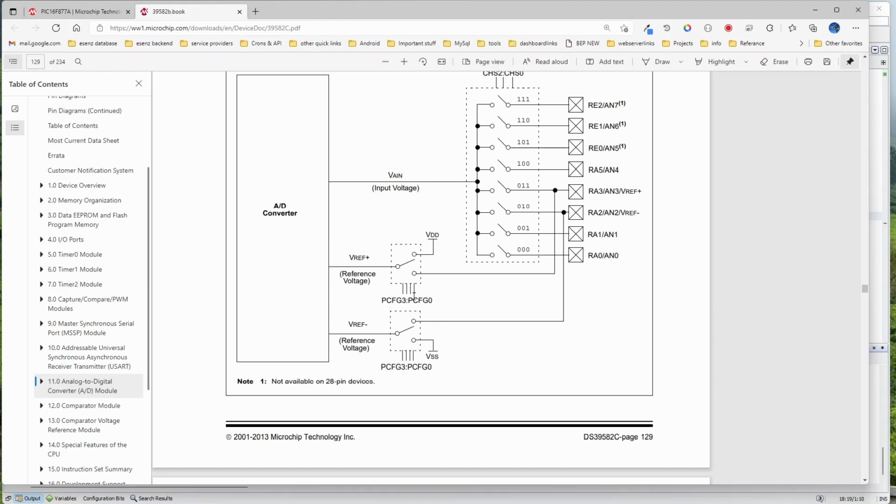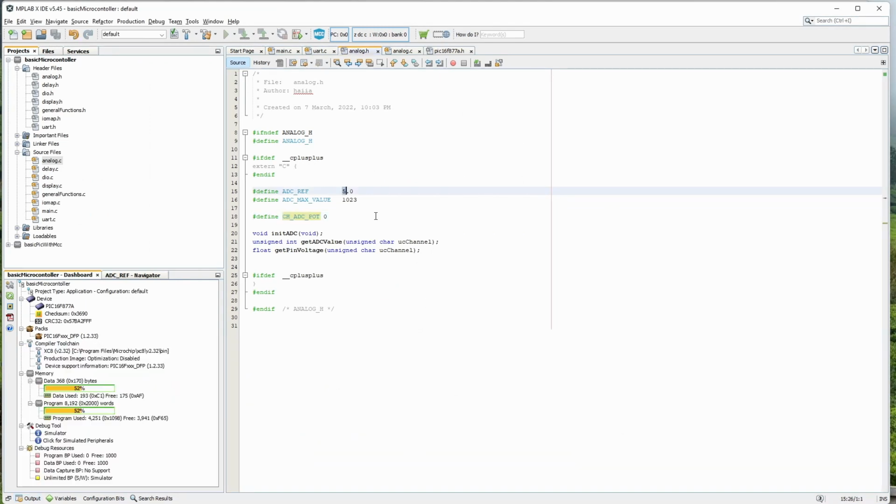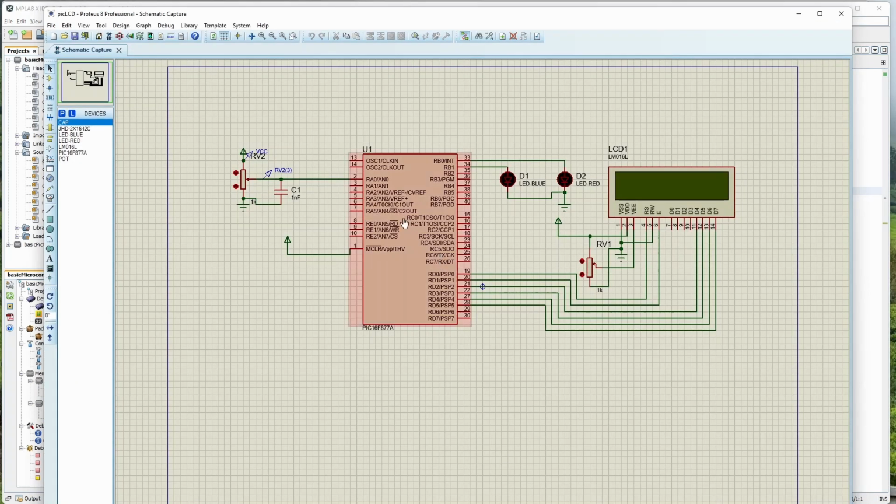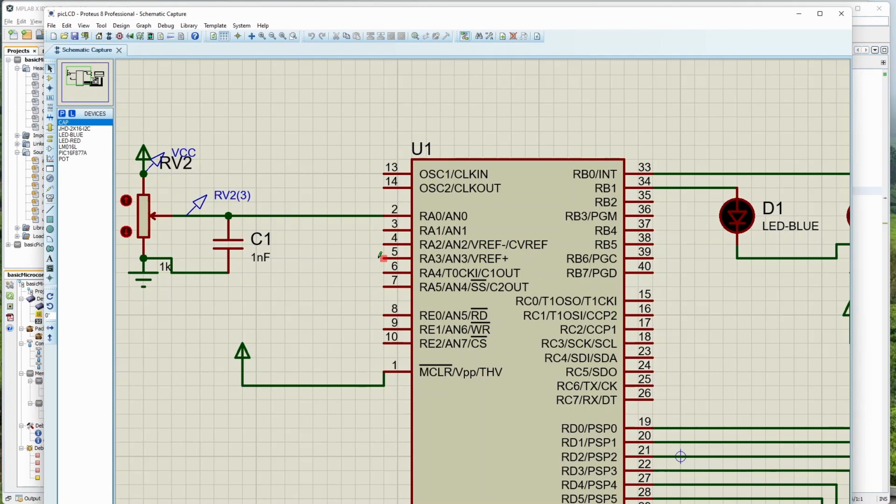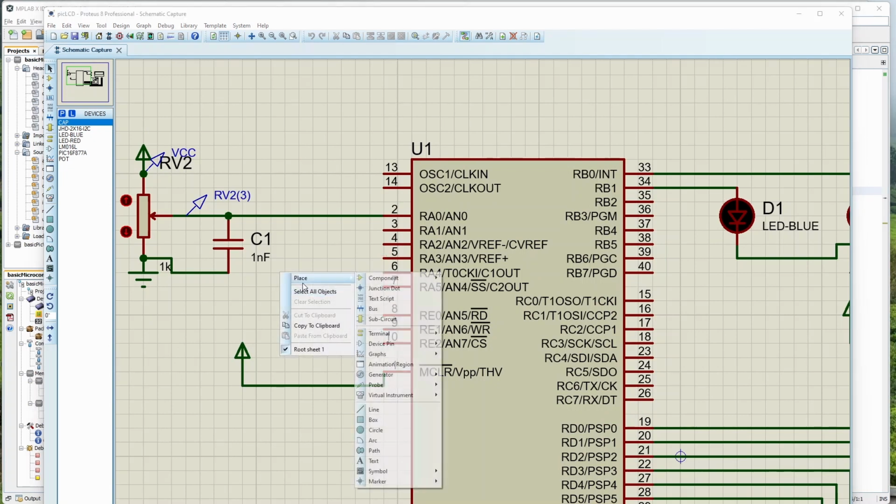Now as soon as you turn on the relay, what happens? The relay is a slight load, or if you turn on something higher, your supply voltage will dip slightly, maybe to 4.9. So now the ADC value will be calculated based on 4.9 volts of the processor, but for the ADC internal calculation, we have assumed 5 volts. In these kinds of cases where the supply voltage may fluctuate, either because of load or input voltage variation, your ADC value will not be accurate. In that case, we have to use an external reference. That is one situation where you can give your own reference.